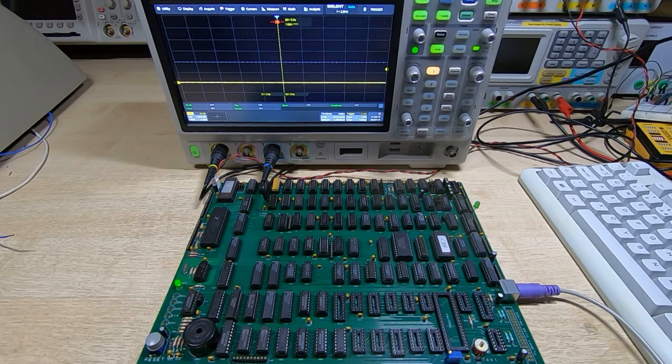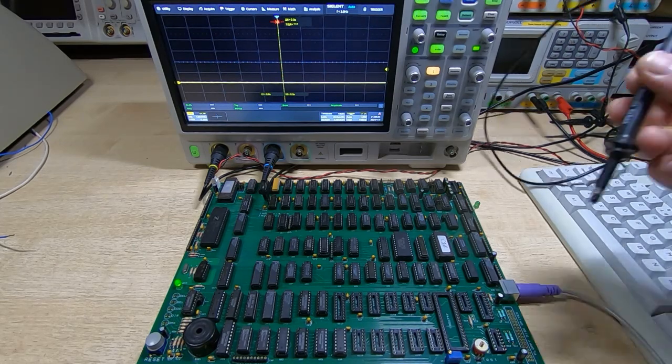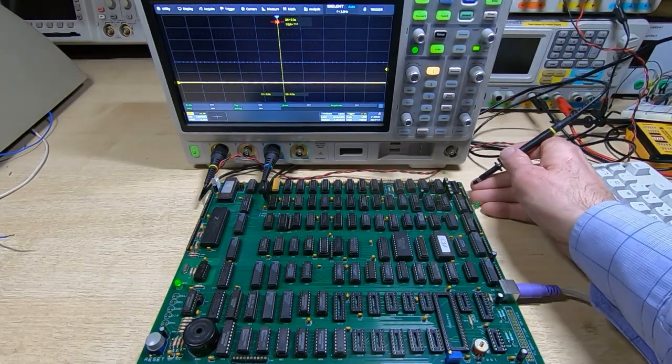That's promising so far. The LED is on. Let's see if it goes out. Now it's gone out. We're drawing just under 1.2 amps, which is exactly what was expected. Now what we can also do at this point is use the scope to see if we're getting anything out of the video.